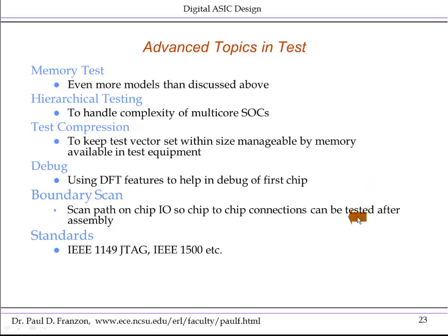I did not talk about boundary scan. That is, the chip I/Os themselves are connected to the external world via a scannable flip-flop chain. The purpose of this is to be able to test the connections between the chips using these boundary scan registers.